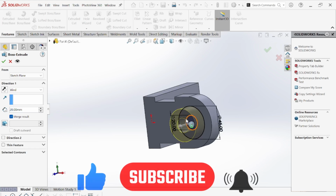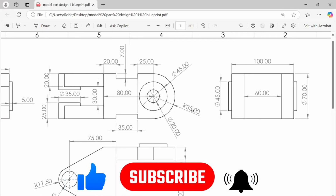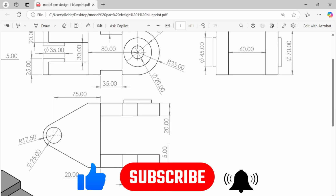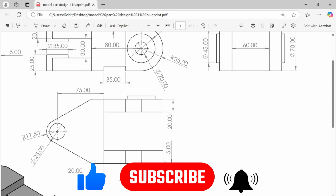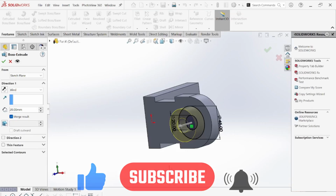Now we need to extrude this one in this direction. And how much do we need to extrude? Come here. Yeah, here is the dimension given. We need to extrude this one around 5 mm. Right? 5 mm. Here you see, we are making this part. So come here. Give dimension 5. Simply make this one 5 and make this one okay.